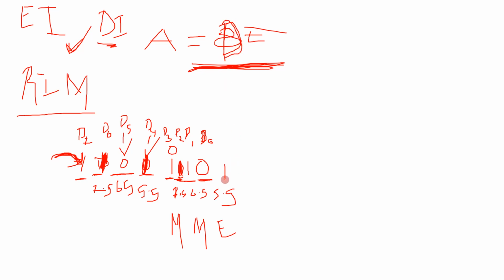So this is what these bits mean in the RIM instruction and the SIM instruction. The difference between the RIM instruction and the SIM instruction is that SIM is used to set the interrupts, or to mask or unmask the interrupts.